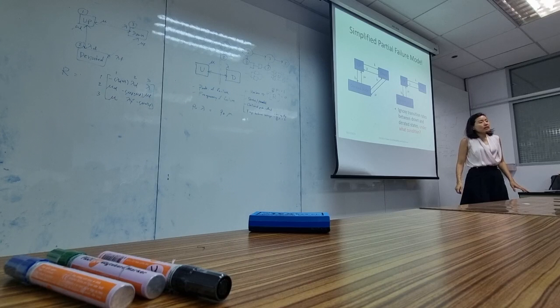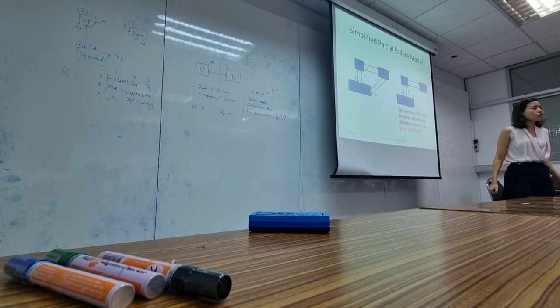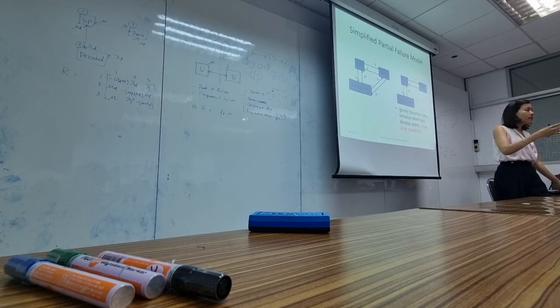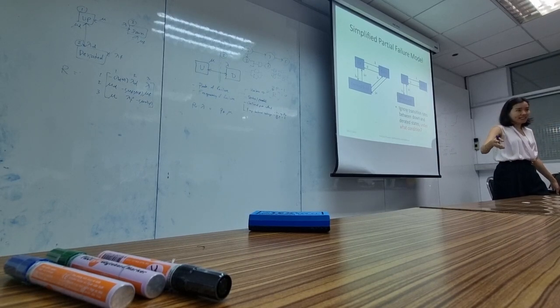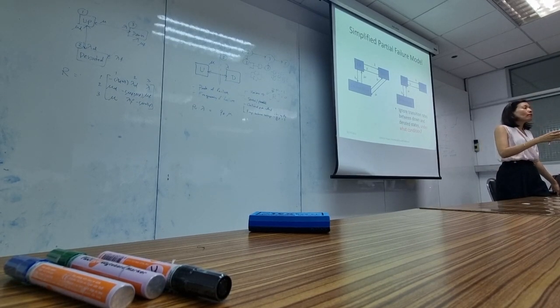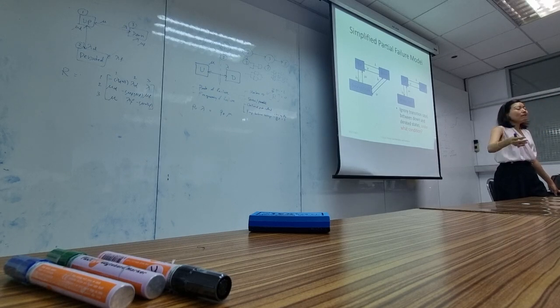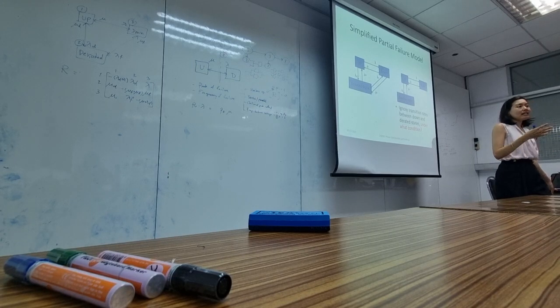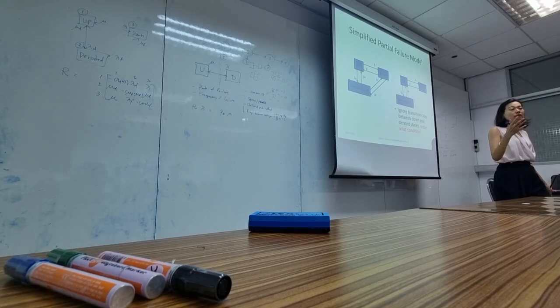Now you might have some confusion about why we choose to use mu or lambda. Most of the time we choose lambda to represent the failure rates, and mu to represent the repair rate. So lambda should be from the better state to the worse state, and mu from the worst state up to the better state. But there is no differentiation between these two in terms of representing the transition rate.